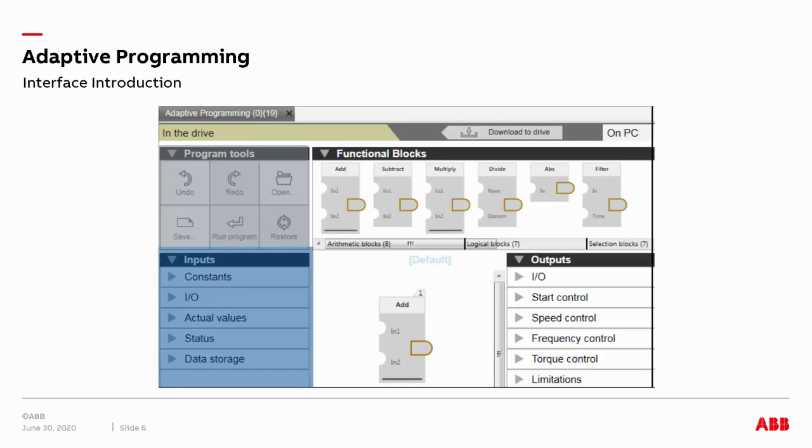Next, you have the input section, which is down in that bottom left. It's going to be anything that goes on the left-hand side of the blocks, and we'll get into the anatomy of what a function block is and how they work a little bit later, so that'll make more sense. But any of you that have programmed with function block editors in the past, like LabVIEW, this will make a lot of sense. This is just everything that goes on the left side of the blocks. We follow that up by the outputs. That's everything that goes on the right side of the blocks and is an output of whatever function we run through.